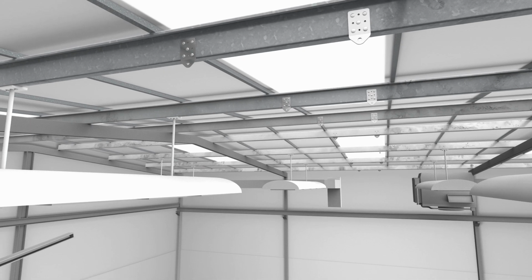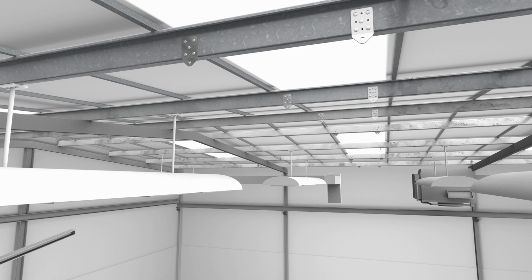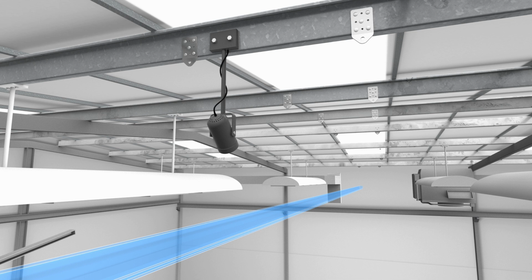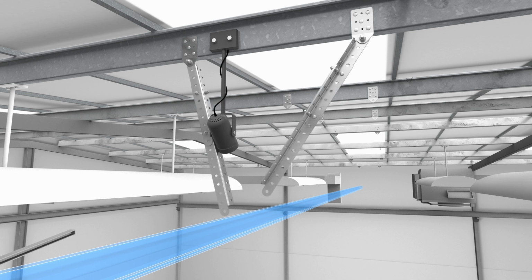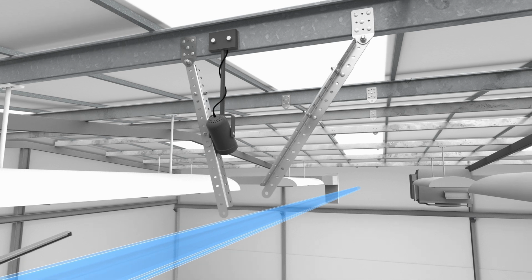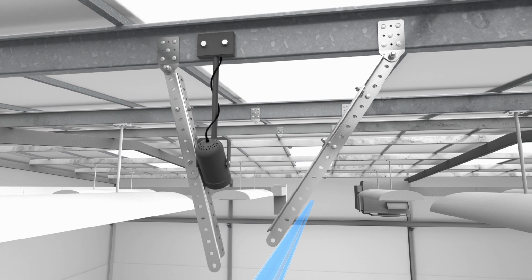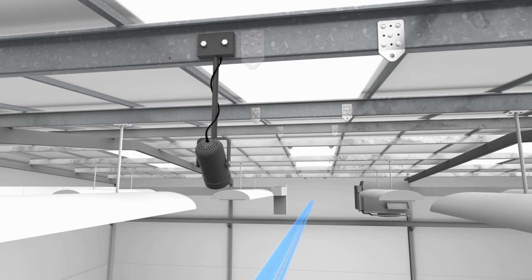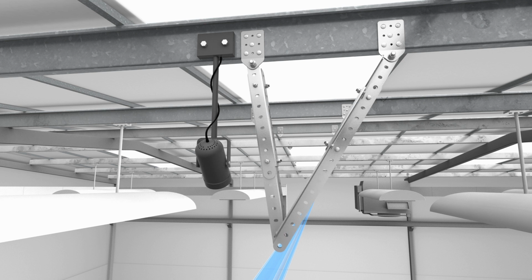Prior to installing the perpendicular purlin brackets, consideration must be given to the trajectory of the hanger link arms onto which the rigid rail will be secured. Where obstructions such as plant, equipment and services will prevent the hanger link arms from joining together to form a central fixing position for the rigid rail, repositioning of the Kee Track system or purlin brackets must be considered.